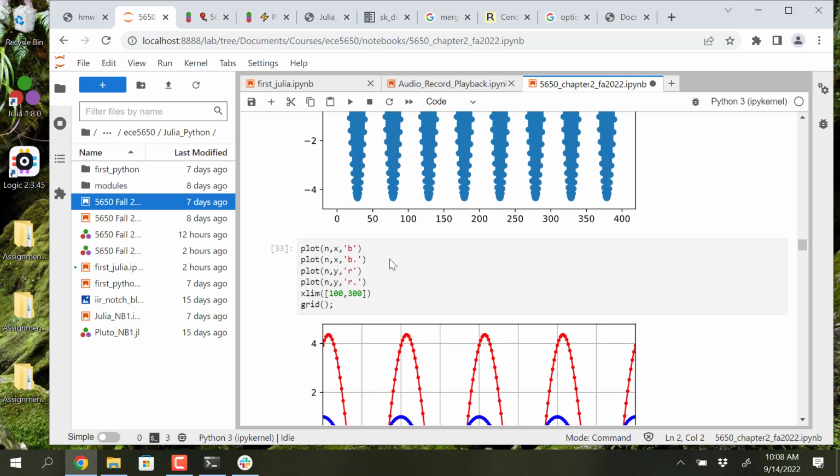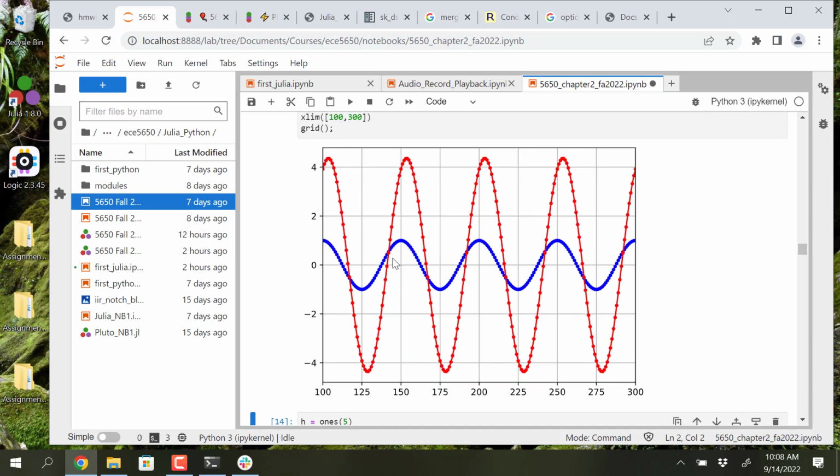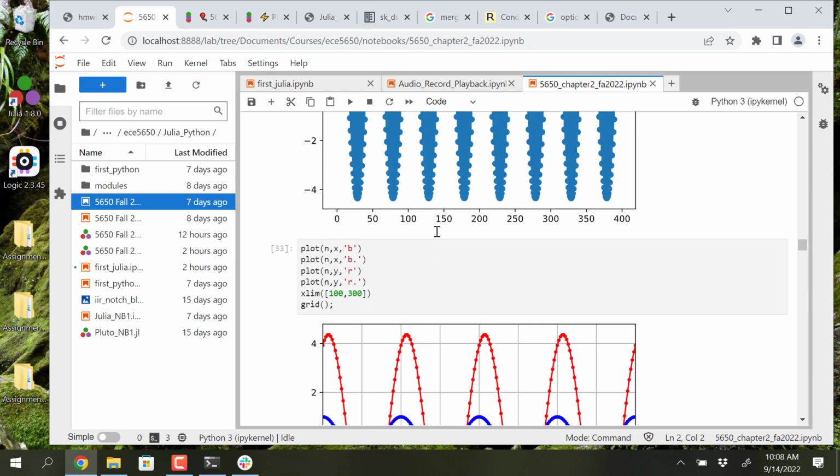And remember, we're talking about frequency response. I'm not so much interested in the difference equation, although we can see what's going on there. We can see our sinusoidal steady state response model assumed the input started at minus infinity, right? So what did I just do to kind of deal with that? I just moved myself down into where I was in steady state. Is that okay? I mean, I'm just working in present time, and I just move out of ways, and I'm in steady state. So I can see the phase shift, and I should be able to pick up the phase shift at this frequency.